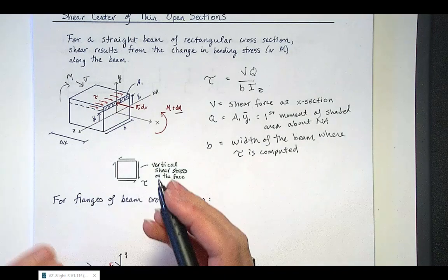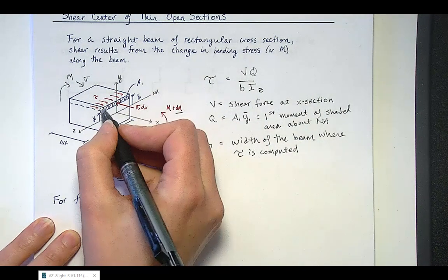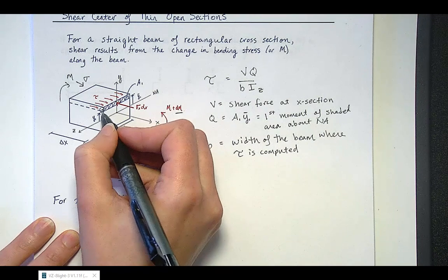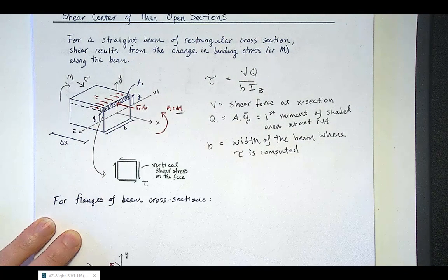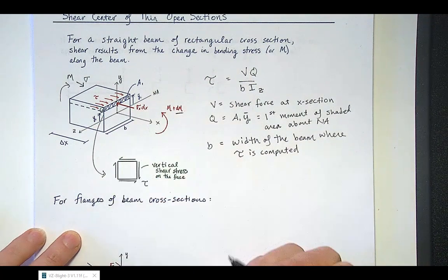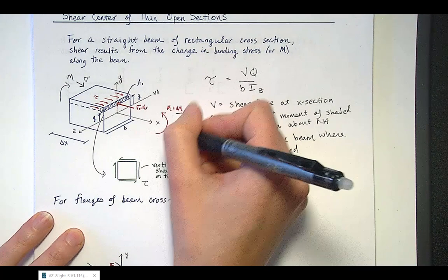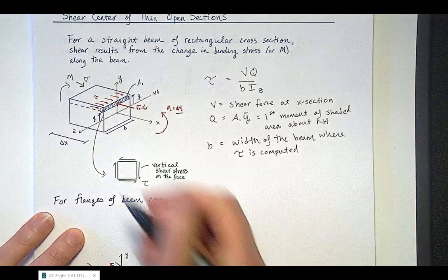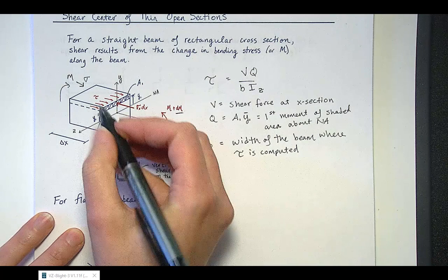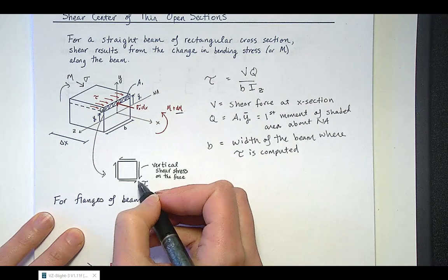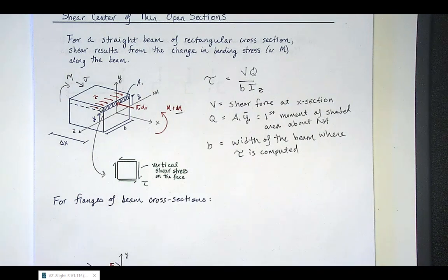So if we consider a small piece, it's already kind of hard to tell, but there's a little green square along the side of our segment, and we blow it up. The shear stresses acting on that segment would look like this, due to positive moment causing a downward shear on this face, resulting in a downward shear stress on the face of the square that is adjacent to our cross-section. And then the heads and tails match.